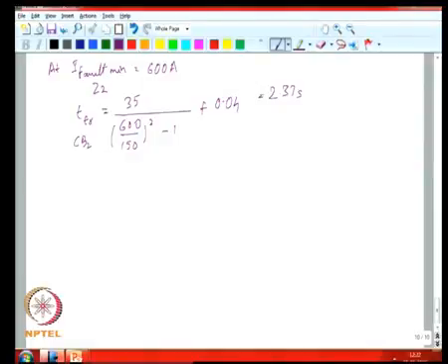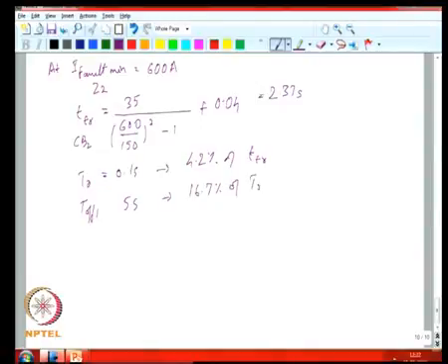If you look at your T naught, in this case 0.1 second, this corresponds to 4.2% of TTR. If you look at T off 1 of 5 seconds, it is 16.7% of T reset. So, again the breaker is fully reset at this particular point.